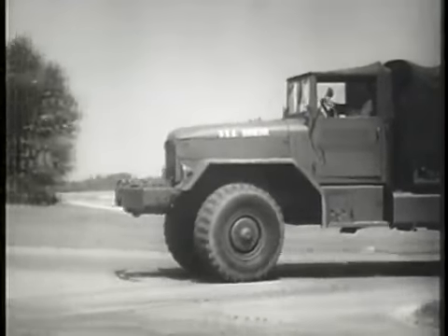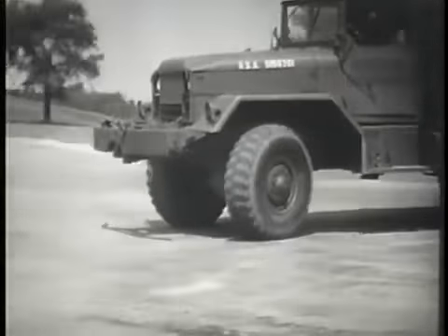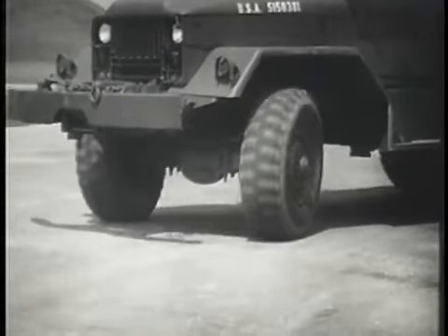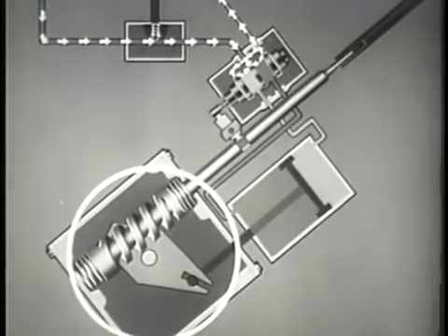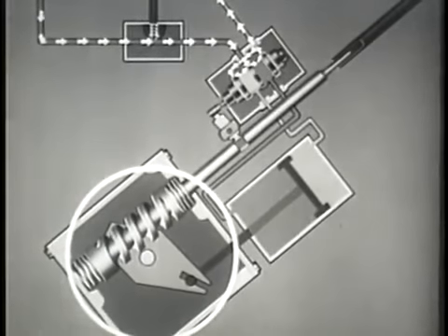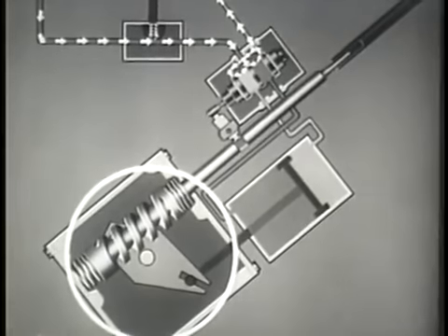When the front wheels are held in a constant turn, the cam will not be rotated. The Pitman arm shaft lever is held stationary toward one end of the steering cam by the increased pressure on one side of the piston.